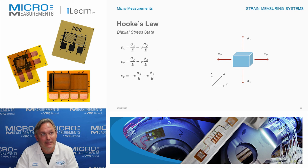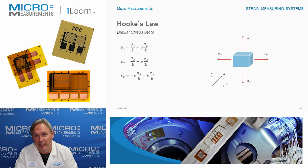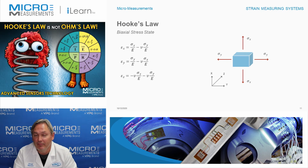And the good news for us is that this is as complicated as it gets when solving for a stress field with strain gauges, because strain gauges will measure the in-plane surface strain. The Z direction, they can't measure. That's into the thickness of the material. So we don't have to look at Hooke's laws for a triaxial stress state, only biaxial, because the strain gauge is truly a surface strain measurement.